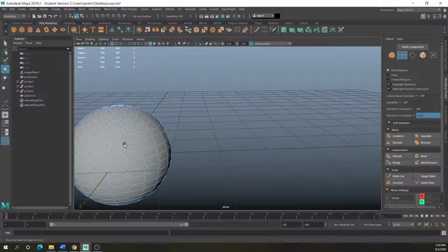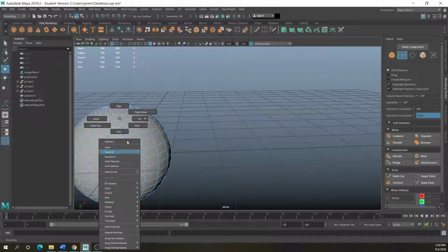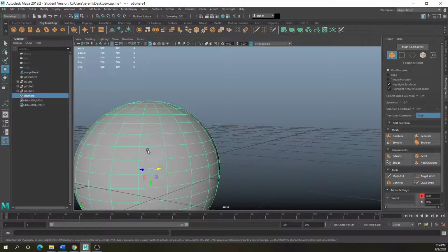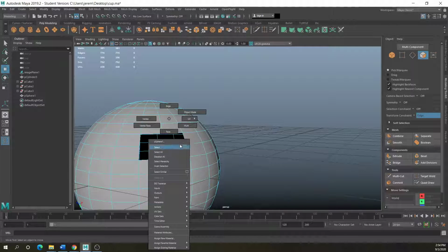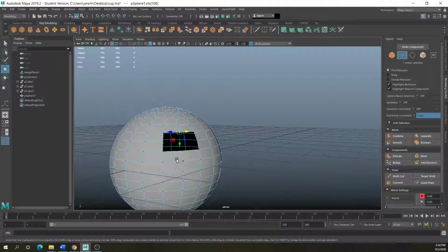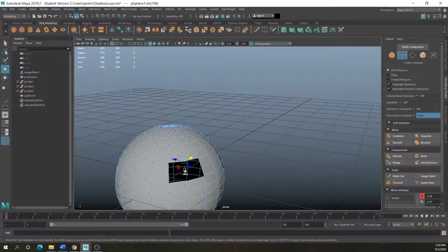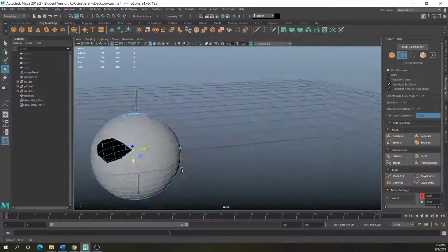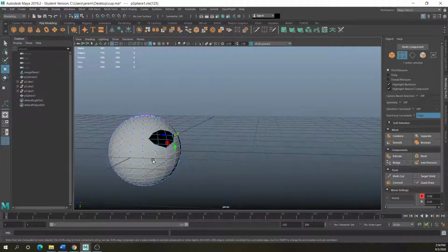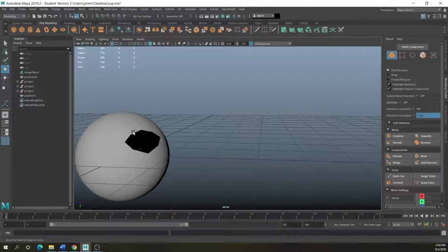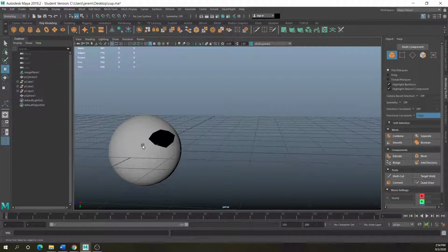So in other words, if I wanted to kind of create like a hole shape here out of this right here, these 4 divisions, or no, let's go like delete, delete, delete. I would select my vertex and I have it on edge slide. So now I can kind of actually push up, push this one to the side, push this one down, push that one to the side. So now basically I didn't slide it off the tool itself. So, and as we talked about extruding on paths, you could actually draw a curve coming out of there and extrude this shape going around on your curved path.